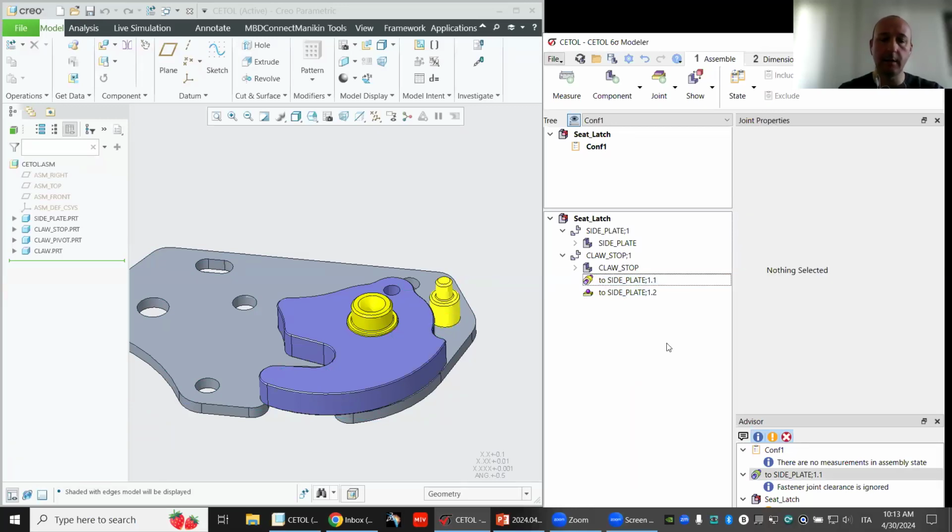Consider that in a tolerance propagation model, the so-called joints are used to define in which way the parts are touching together. And this is really important in a tolerance propagation model because this governs how the errors, the tolerances, propagate inside the tolerance model. So it is a way to define how errors move from one part to another inside our assembly.